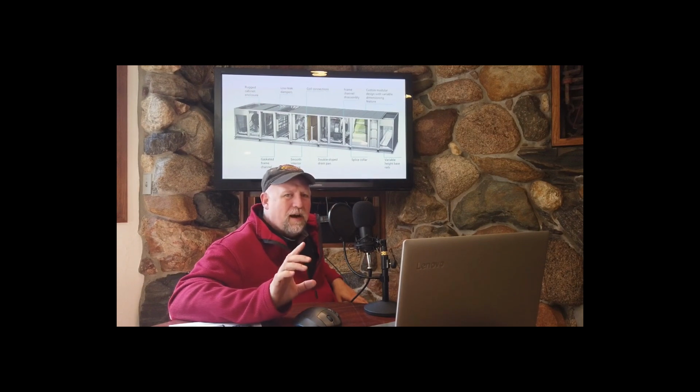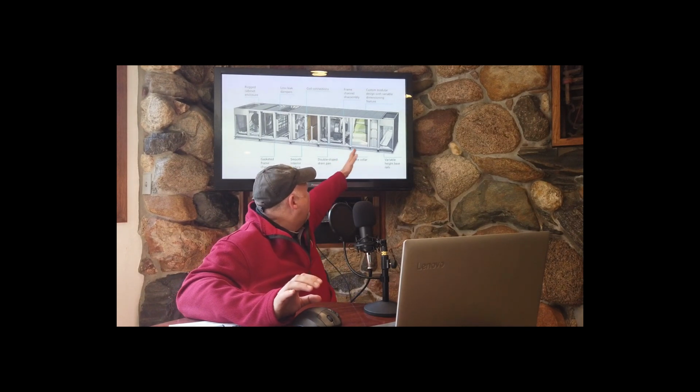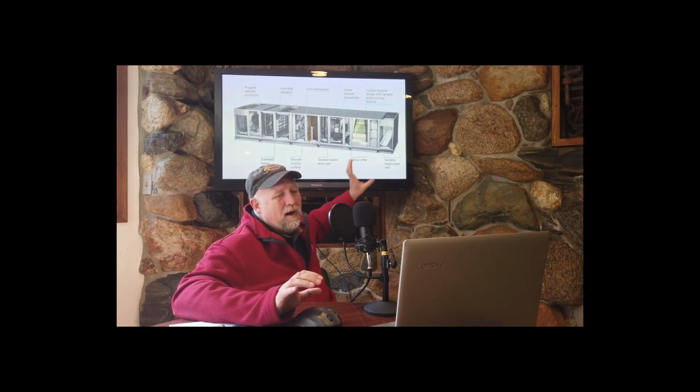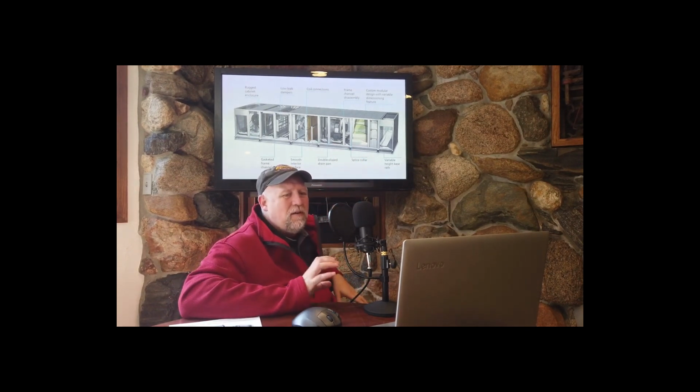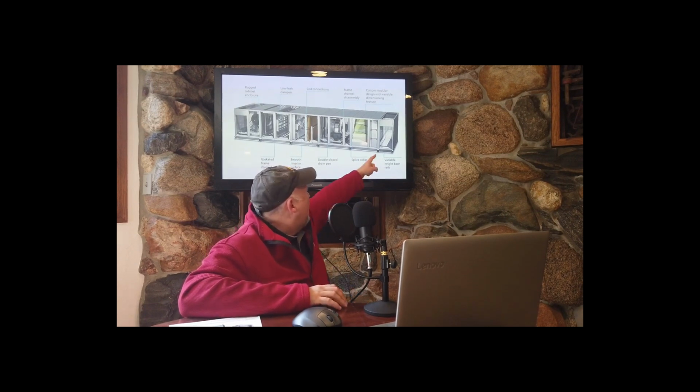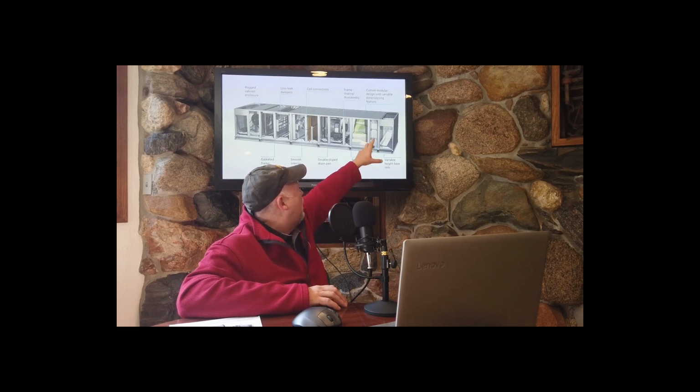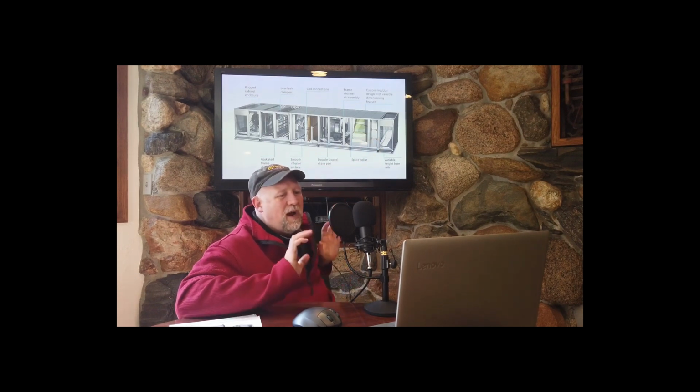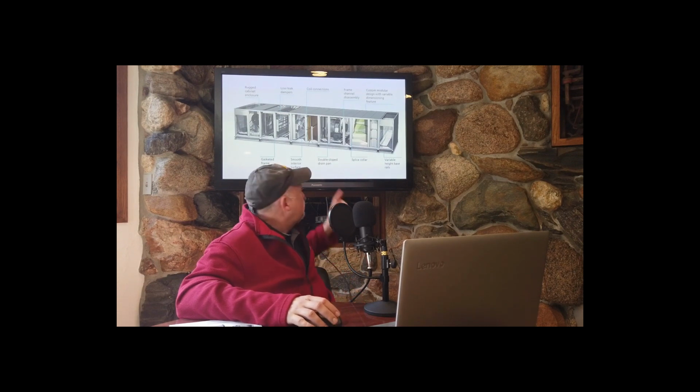Remember, not all air handlers will have a sound attenuator, but an important thing here is this adds a lot of length to the overall air handler. Sound attenuators take up a bunch of space. And then from the outlet, we have the plenum, where they take taps off in all directions for air to go down the ductwork.